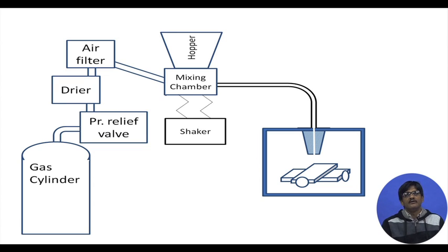So, we cannot have a large outlet diameter of the nozzle, and therefore we cannot have agglomeration of the abrasive particles, which are 10 to 15 microns in diameter. Moreover, when the air is entering the mixing chamber, it might be entering with a still small diameter, but that is a different story altogether, because at that time it is not mixed up with abrasives.